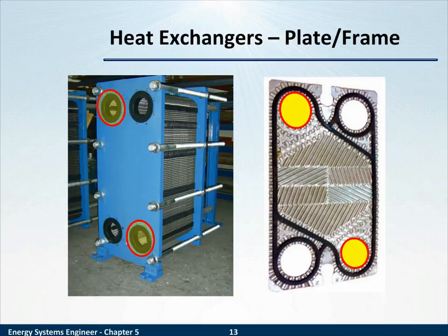As I was mentioning on the previous slide, we would have two additional slides showing configurations of waste heat recovery systems, and here's one. They call it a plate and frame heat exchanger. And the reason it's called plate and frame is because it's composed of these plates that are sandwiched together and held together with this, in this case, blue frame. We've highlighted in yellow how the flow in this cross-current plate and frame heat exchanger works.